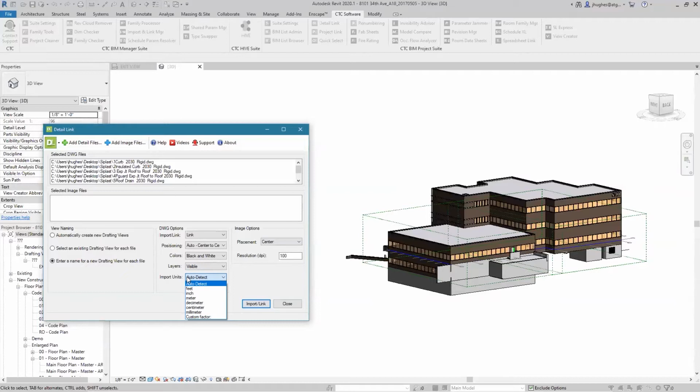If you get a survey from a surveyor or a civil engineer and they're using decimal feet, it will throw AutoCAD for a loop, and you will end up shrinking things by 1/12 or multiplying it by 12 all the time. With Revit, just leave it on auto detect. If it somehow ever fails you, then yes, you could choose which unit type you might want to specify.